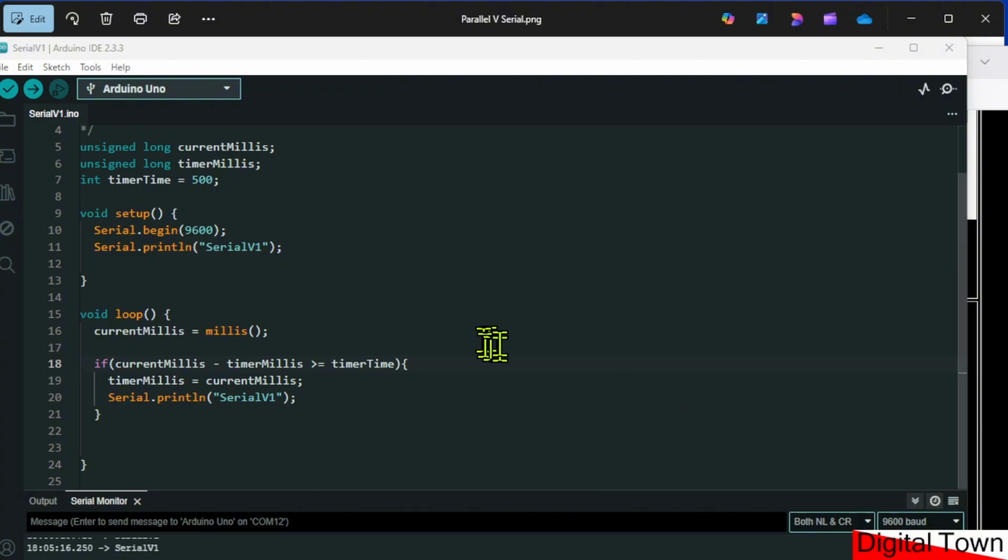Now, if we go to the Arduino IDE, if we think back, going back to lesson 2, and we've used it in just about every other lesson, when we start the serial communication, we just tend to put in serial.begin and then the baud rate, the speed that we want the system to read at or transmit at.